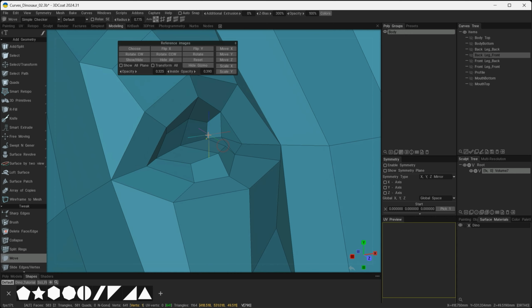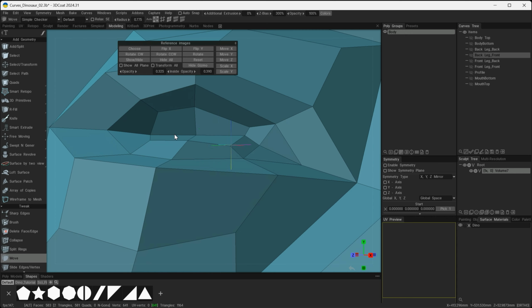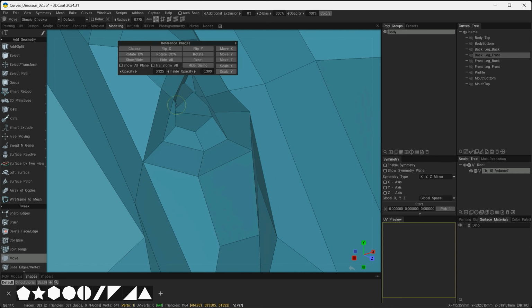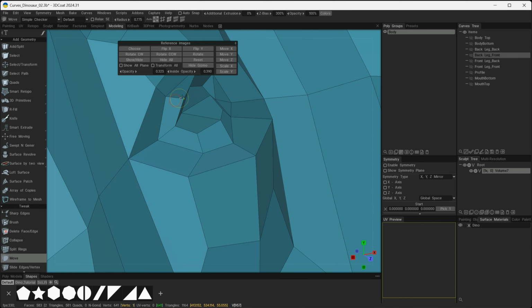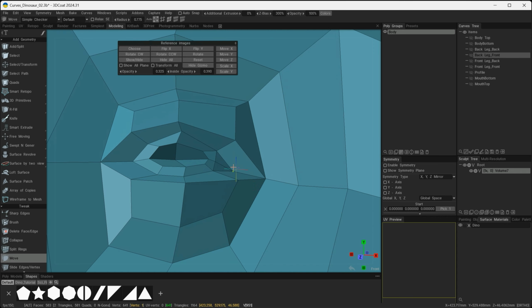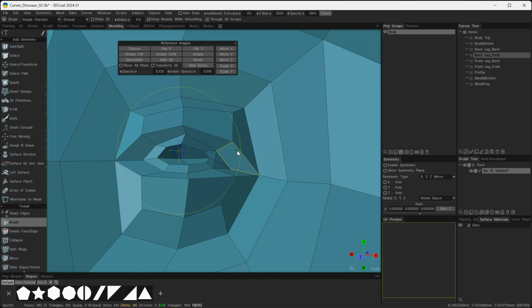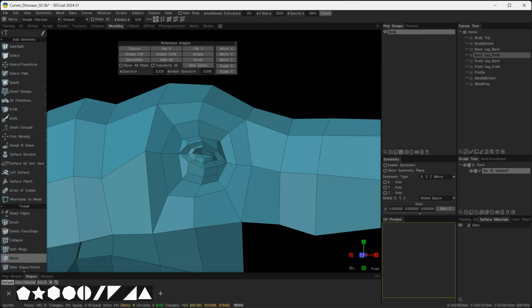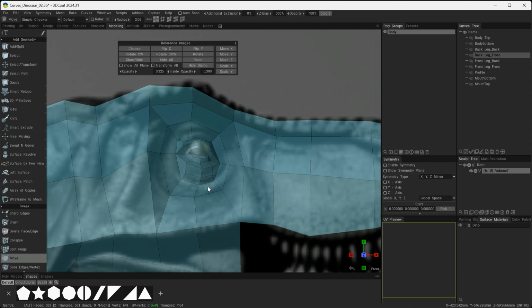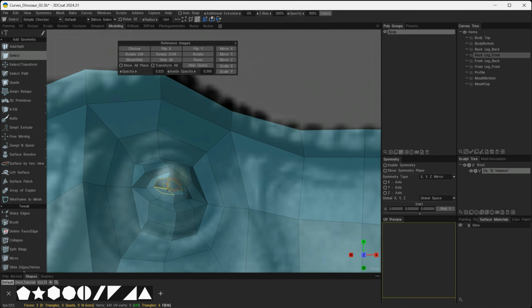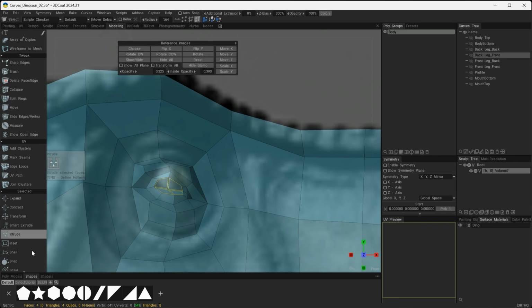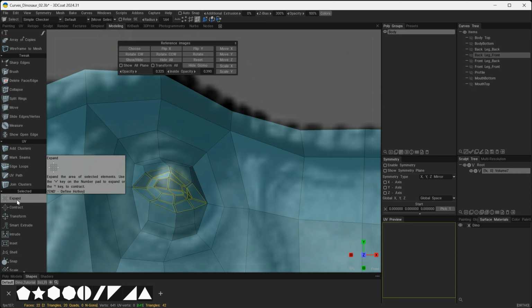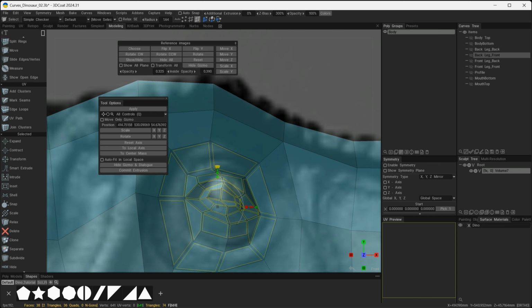Just trying to get those creases and little folds that are evident on the reference. Just use a bigger brush on here and pull this geometry around a little bit more. Let's just have one quick look at our reference. Snap that back. I'm going to select these inner polys here. Then I'll go down here to expand, just expand these out, select those ones as well, use my transform tool and maybe just move these up a little bit higher to where the eye shape is.